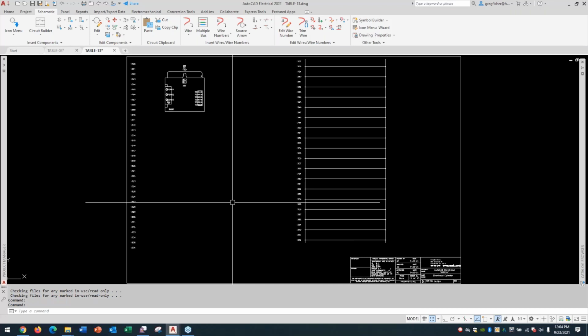It's inevitable. You'll look at that table list and say, I'm going to create a table for an HMI. There are no tables for HMIs in the parts database. And you'll run into that here and there, especially with new components that hit the market. So you really want to familiarize yourself with how you can add the proper tables. And it's really about organizing your parts database in general.